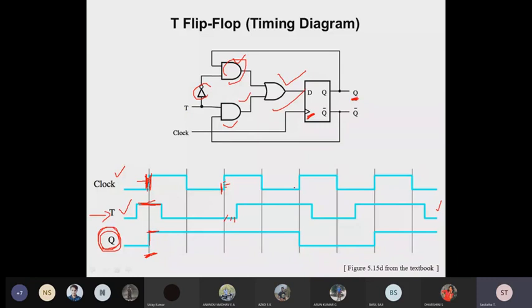So till the next phase, it continues to lie in the same portion only. But again, during the next positive clock trigger, so next positive edge clock triggering, what happens? Purely it suggests it's in a positive pulse, but previously again due to the application of the propagation delay here, it will not immediately reflect that, you know very well, right? So whatever appeared in the previous pulse is reflected here due to the propagation delay. This and all you might have studied in the second unit, combinational circuits, right? So the propagation delay concept and all you might have studied.